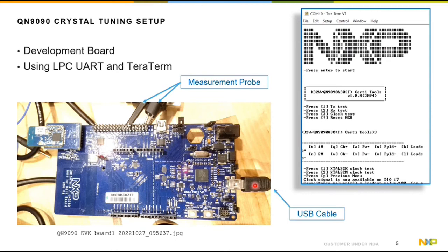If you use this USB cable on the board, that is not an FTDI serial port. That's a different serial port, J-Link, or a different type of serial port from this IC. You want to use this port here to get your terminal emulation for this example for FTDI. If I connect it properly, I would then see feedback coming back from my board. And so now let me break away and show you how those connections are done.